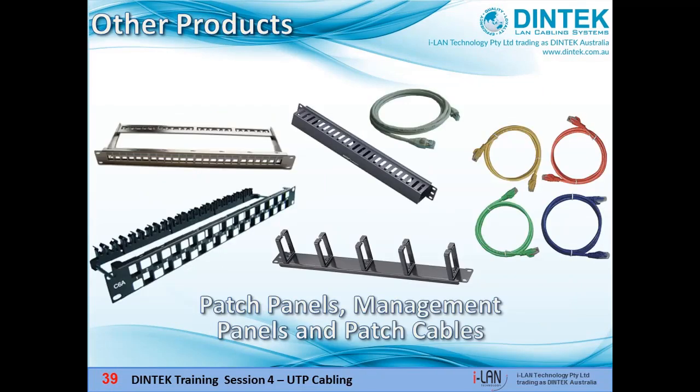DINTEK also have a wide range of patch and management panels, including shielded patch panels and cassette patch panels for Cat6a and Cat7. And of course cables and patch leads, which come in different colours with different lengths, with either a PVC or an LSZH cable jacket. LSZH stands for Low Smoke Zero Halogen, which means it emits limited smoke and no toxic fumes when exposed to high sources of heat or fire.